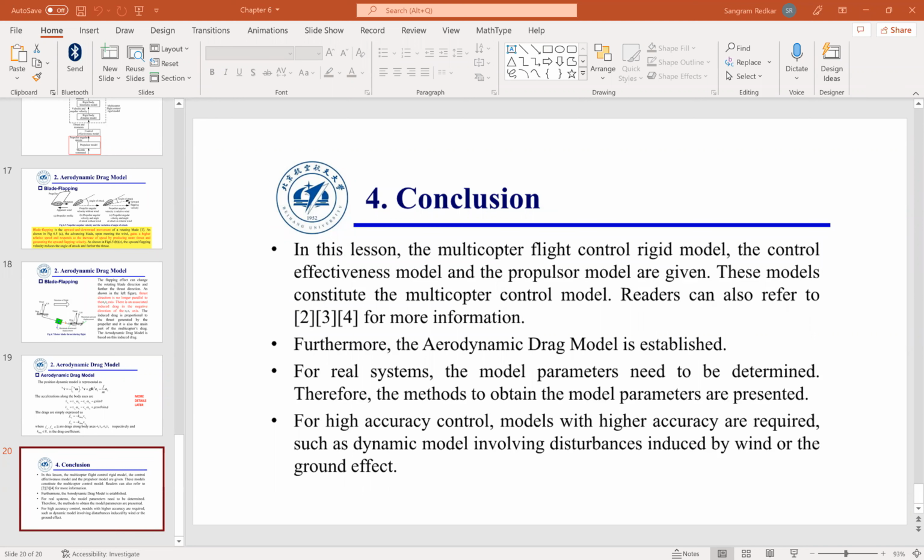You remember this? Jacobian, linear, angular Jacobian of angular velocity, and then finally we combined the whole thing, and then we said that you have something like omega 1, omega 2, omega 3, and then you have omega x, omega y, omega z, and this is a Jacobian of angular velocity. Could you explain omega 1 to 3 in this context? Because in that, omega 1, 2, 3 are the rotation rates about individual phase. Is it in the ABCF or CCCF? I'm on robotics 1, not in robotics 2. In that context, what I mean by this is omega 1 is the angular velocity of the joint 1. Omega 2 is the angular velocity of joint 2. And omega 3 is angular velocity of joint 3. Remember? Yeah, that part is. Okay.